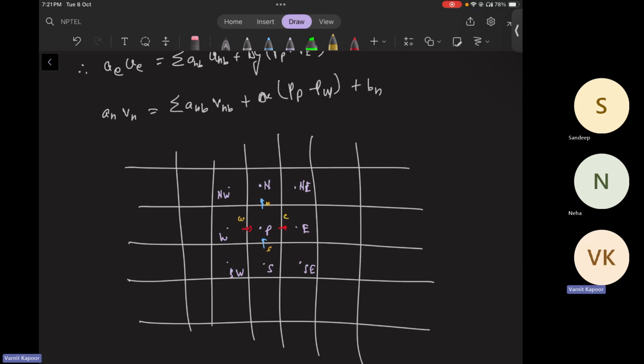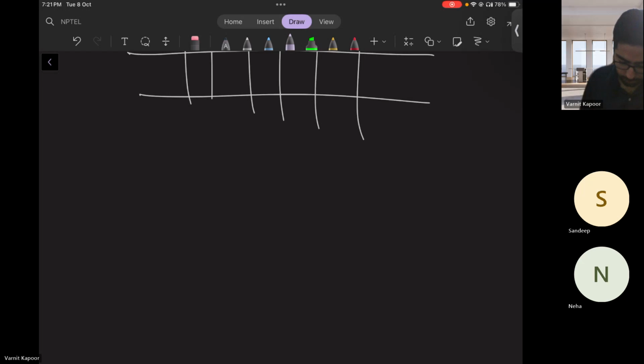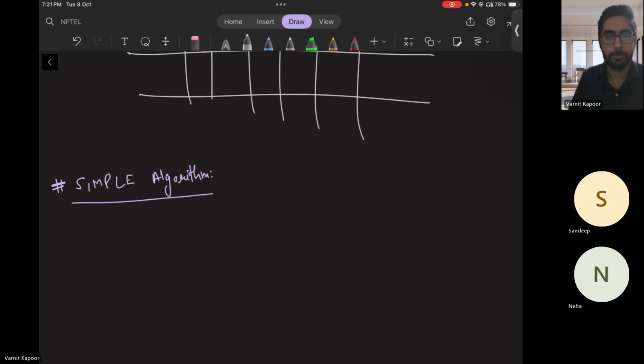Okay, let's start with the SIMPLE algorithm. SIMPLE is a semi-implicit method for pressure-linked equations, which addresses both the difficulties: use of a staggered grid approach, and creating a discrete equation of pressure from the discrete continuity equation and the discrete momentum equations. In detail, everything has been discussed.